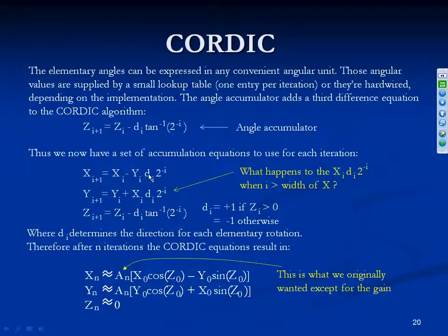If let's say d was a 1, for instance, I'm going to multiply y times 2 to the minus I. What is that doing? Can anybody tell me? How would you do that in hardware, in Verilog? Just a left shift or a selection. Yeah, it's just a right shift. So we just shift it right by I places, according to I.